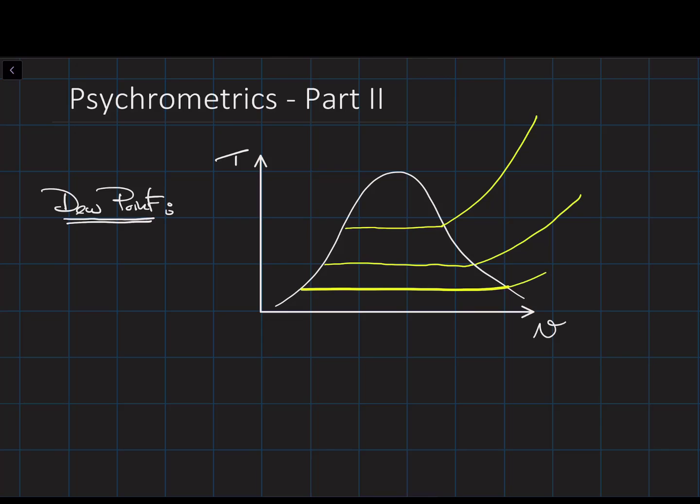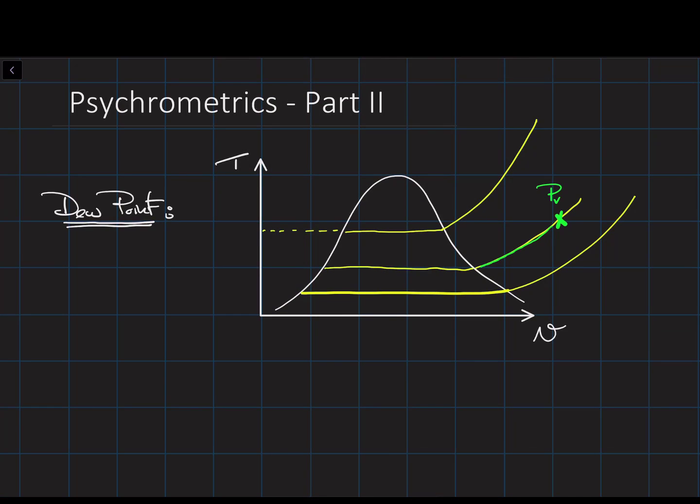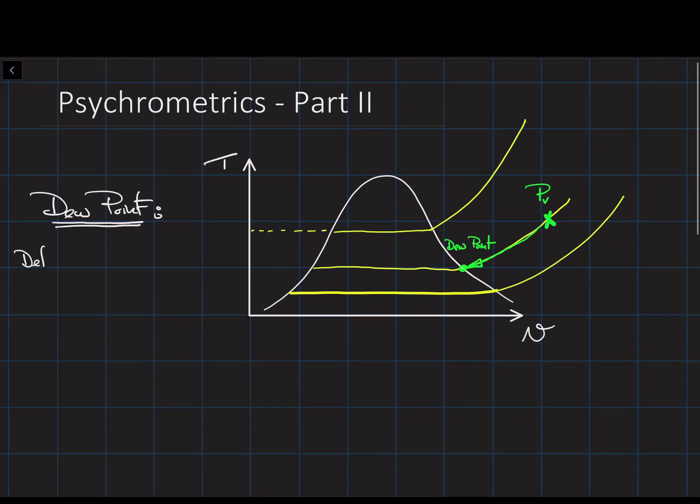So first we're going to start by defining the dew point, and it's best illustrated on a TS diagram as such, and I'm going to put 3 isobars on this TS diagram. You'll see why in a moment. It'll make sense then. But right now, let's say I got these 3 different isobars on the TS diagram for water, and let's say the top one is at 70 degrees Fahrenheit. And let's just say that the middle one is where my moist air sample is on.